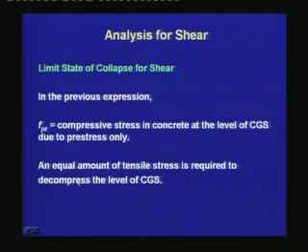Thus, if we calculate the compressive stress in concrete at the level of CGS, we can find out the moment which will generate an equal and opposite tensile stress at the level of CGS, which will thus decompress the concrete at the level of CGS.